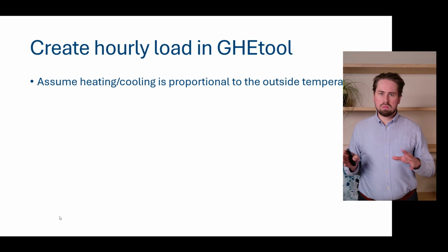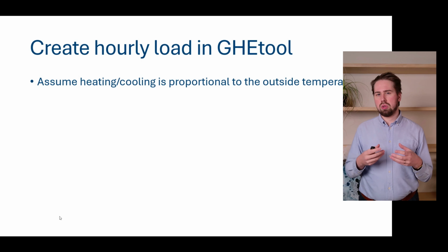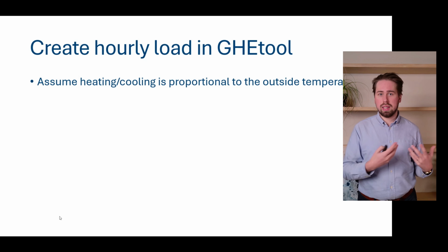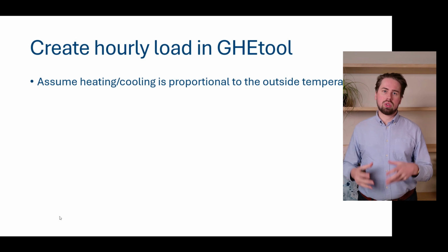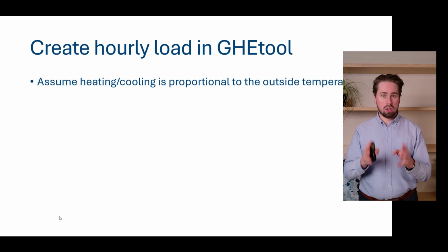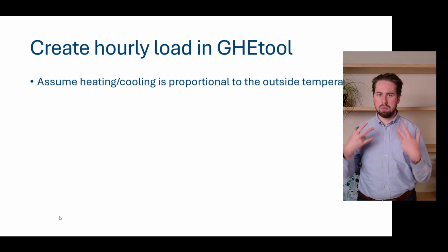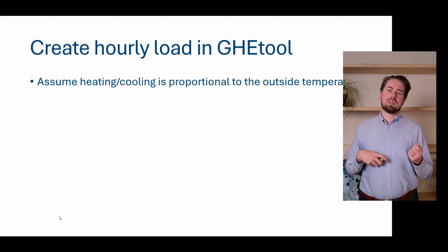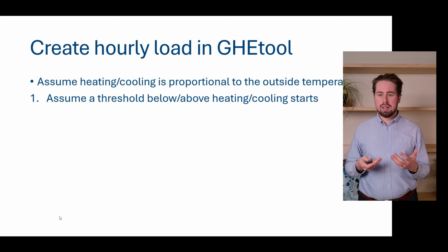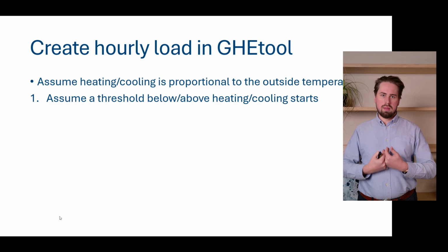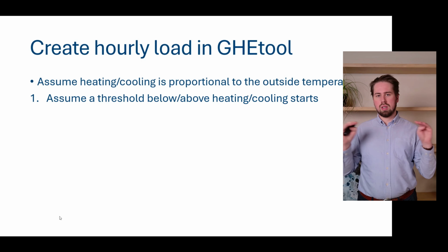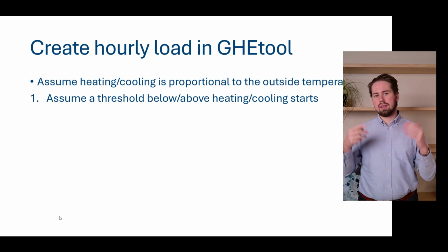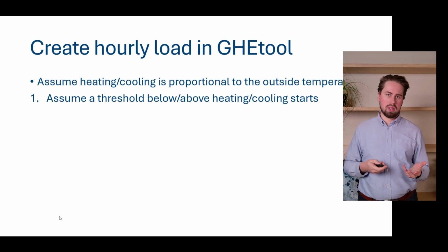Now, we will see this later, but hourly profiles can give you quite a lot of insight in your design, but most often they're not available and we're stuck with monthly estimates. So that's why in GHG Tool Cloud, we also developed a method to take your estimates, your energy demands, your peak demands, and to upscale them to an hourly load profile. And this we do with a method based on these heating degree days. So what we do is we say, okay, let's start with a threshold temperature and assume that everything below this threshold temperature needs to be heated, and everything above a threshold needs to be cooled.